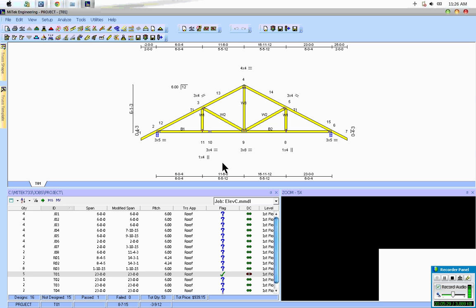That way you eliminate the errors or the possibility of forgetting to update one specific elevation. So that job comes up for a reproduction, you send it out thinking it's good, well, it didn't get updated like the B elevation did on the C elevation, and now you have to go out there and make repairs. This will help alleviate those repairs.